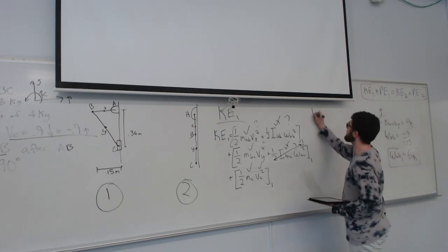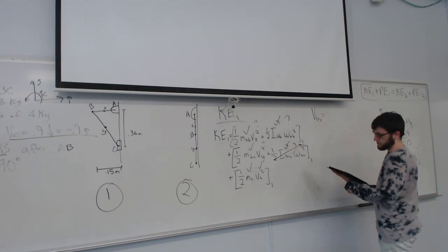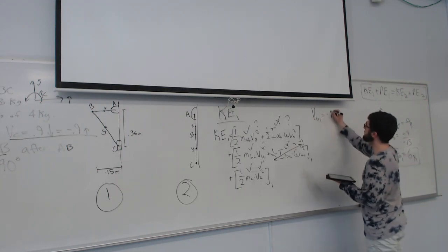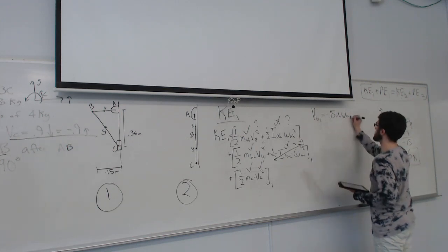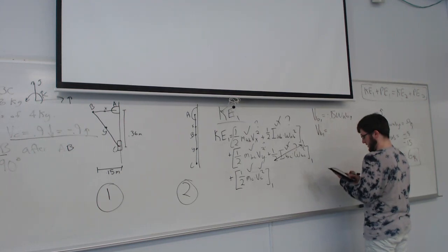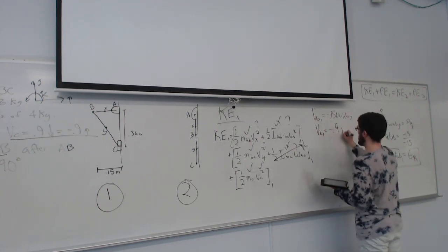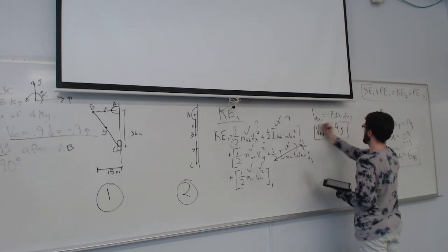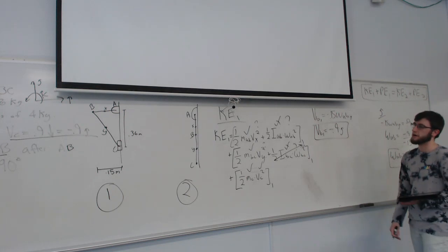Okay, we said velocity of B at 0.1 was equal to negative 0.15 omega AB, and that was in the j direction. So now we can solve that directly. It's just the computation. Velocity of B at 0.1 is negative 0.9 in the j direction.